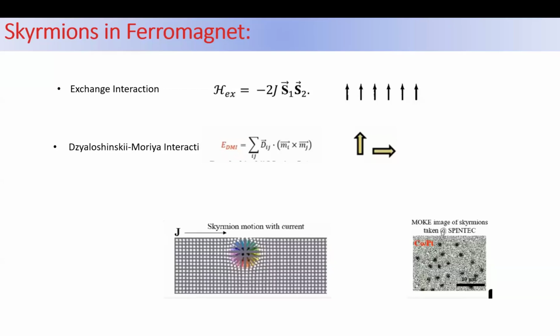Like in a bilayer ferromagnet and heavy metal structure, the skyrmions can be developed by means of current or voltage. And here I consider the generation of skyrmions by using magnetic tunnel junctions on a ferromagnet layer. The skyrmions form at the interface of ferromagnet and heavy metal.